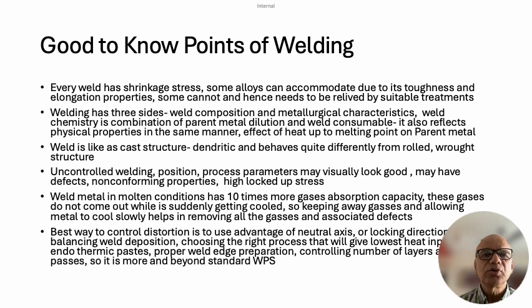Now there are a few good to know points in welding. Every weld has shrinkage stress. We cannot avoid it, because we are going up to the melting point and then trying to solidify. In situ solidification in the weld edge preparation, and that too is not uniform all across. As we are progressing our weld, accordingly the weld is getting progressed and processed, so it takes certain time.